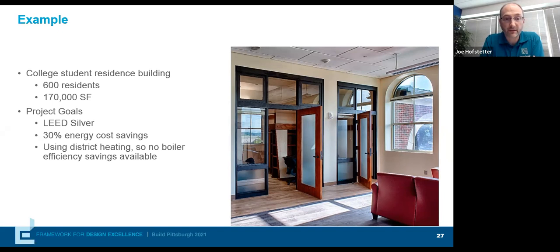And what really drives some of the decision making is that this was a campus and they had the investment in their central utility and plant. They upfront basically flat out said, we are tying this into the district heating system, and we are tying this into the chilled water system. So right then and there, that answers some of our variable questions. It takes some of that equipment out of the discussion about what we are really looking at, because we knew those were going to be fixed variables and there wasn't a lot to change there.